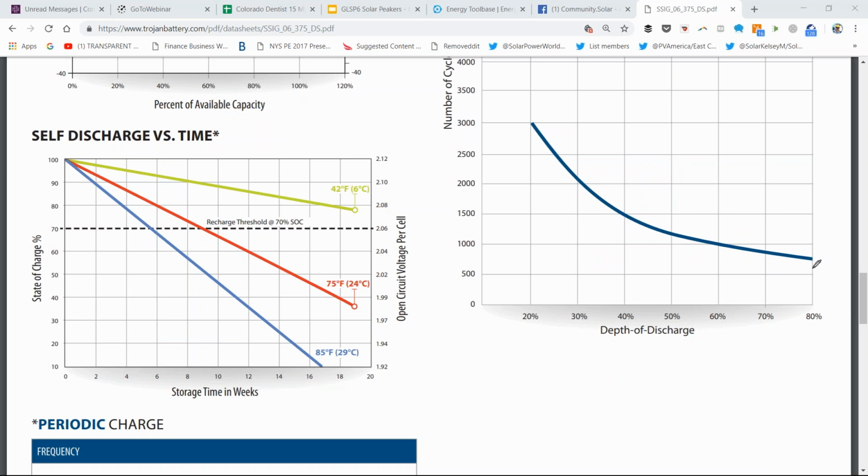On these kinds of charts, the inflection point, say for a non-premium battery, occurs further up so that you can't deep cycle the battery on a daily basis more than 20 to 30% of the battery. Whereas industrial flooded lead acid, the inflection point occurs closer to the 50 to maybe 60% range.